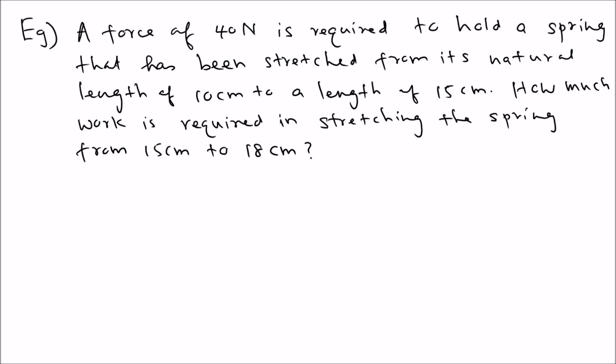The problem says, a force of 40 Newton is required to hold a spring that has been stretched from its natural length. That's very important. You need to find the natural length and stretch from that. The natural length is 10 centimeters, so only if you stretch more than 10 does it apply a force. Hooke's law says the extended length is proportional to the force, so you always need to subtract 10 in this case. From its natural length of 10 centimeters to a length of 15 centimeters, how much work is required in stretching the spring from 15 centimeters to 18 centimeters?